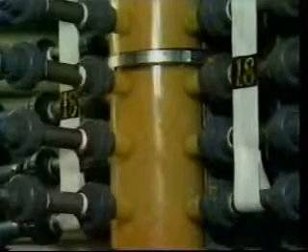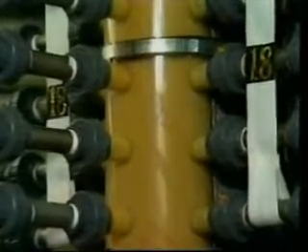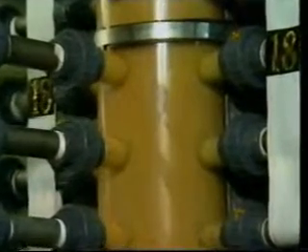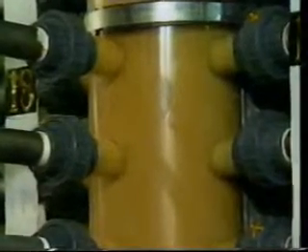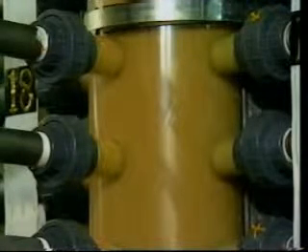Since it's so important that we fill the perforation tunnels with gravel, this is something that is very, very difficult to visualize from the surface. So this gives us a good idea of what to expect when we go to the field. And these designs have been tried in the field. We can vary things like the actual screen size, the wash pipe combination, the gravel pack method. Do we circulate the gravel pack in place or do we squeeze the gravel into the formation?